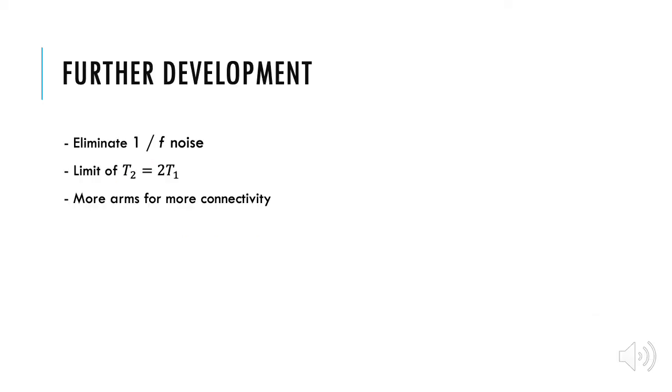For previous research, the main strategy for enhancing the dephasing time in superconducting qubits is focused on quantum circuit design and eliminating the linear noise sensitivity by operating qubits at optimal working points. And there is a second approach, by improving the property of junctions and materials to eliminate sources of 1/f noise. It is a difficult and costly process, but it is likely to benefit a wide range of qubit design when it is successful. In the long run, a combination of both strategies will probably be necessary to realize a scalable design for superconducting quantum computing.